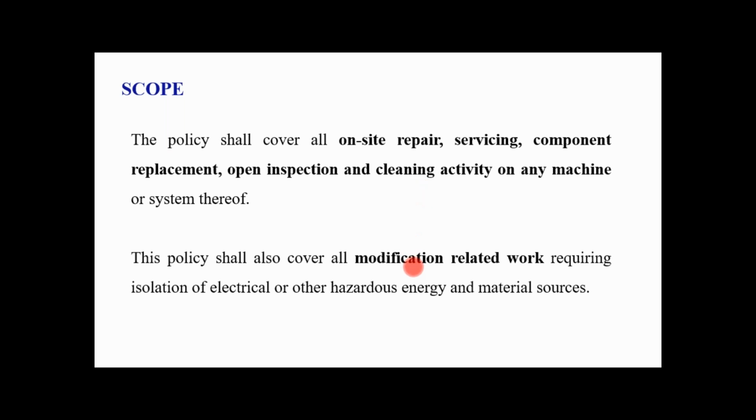Sometimes it also covers all modification related work requiring isolation of electrical or other hazardous energy and material sources. So whenever you are planning a modification in the equipment, in the piping design, or in the equipment design, then you have to apply these LOTO systems to that modification work also.